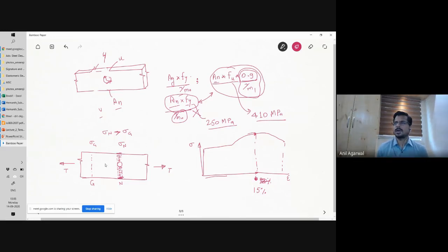Okay, that is the whole diameter. And even of the whole diameter, the entire length will not be yielding. Only where you have the smallest cross section, only that portion will be yielding first. So then you are going to get to 15%. However, here, if the yielding starts, there is no restriction that the yielding should be limited to only here. Yielding can spread here, can happen anywhere. And in fact, once this yielding happens, this section will start moving on this path and the stresses will climb up slightly.